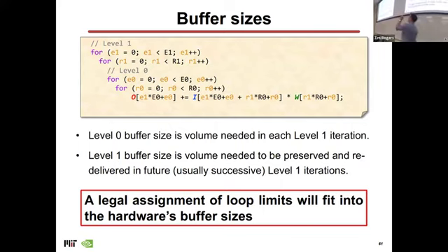Okay, so for these machines to try to keep them efficient, they tend to not use caches, because caches have tag overhead, they have energy overhead, it's harder to make them higher throughput. And if everything is so regular, because I know all of the sizes before I launch the program on the DNN accelerator, I don't need caches. I can just have the software basically tile things for me. As long as the software is adhering to these constraints, that you've got to make sure that everything fits inside the L0 buffer before you do this inner loop, and then the L1 buffer is big enough to store a couple iterations of L0, or at least 2, right? So you can feed the thing as it's processing the next inner loop. Then you're fine, and you don't need a cache.